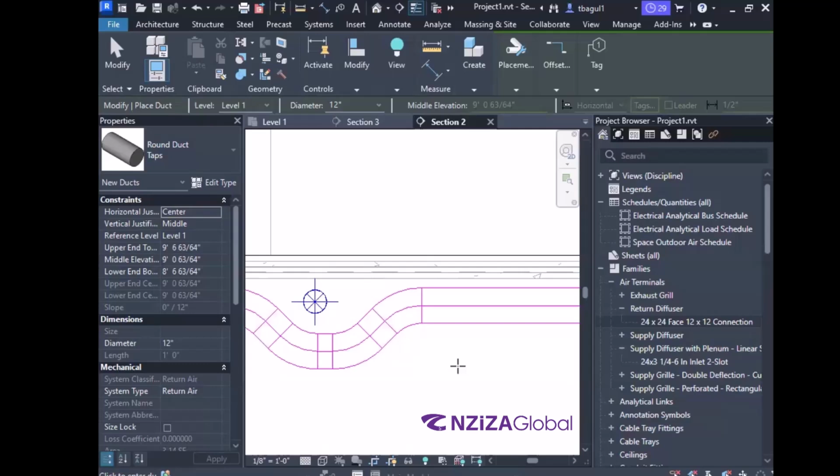Don't use the unions. Is this coordination understood properly? So just like this, make sure you avoid sloped pipes. Sloped pipes will come into the picture when we are talking about sanitary waste and soil pipes. As per the codes, you would require a minimum slope for the pipes. Whenever you have something that is sloped, if you are working on a restaurant project, there will be grease ducts. Grease ducts are sloped.